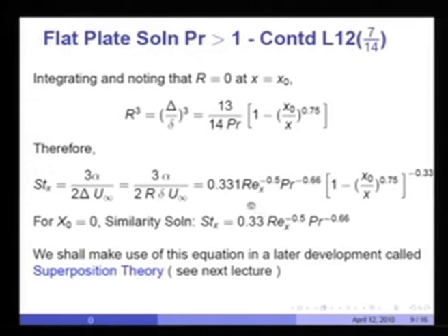And you can see that in spite of a very simple temperature profile and velocity profile, we have obtained an extremely accurate solution using integral method. But you can see that whereas similarity solution required solution of 3 ODEs, the integral solution is simply pencil and paper method and produces many a times extremely accurate results.